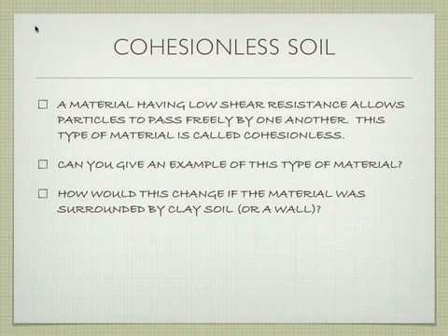But if it's not surrounded by that, it's going to have a tendency to slide, which is going to cause all the issues like you guys have seen with the Pacifica buildings that are hanging on the edge of the cliff that have been there for however many years. Every year they come up on the news, oh, the rain's coming and they're going to fall off the cliff. You guys know what I'm talking about? They're built on sand. There is no boundary holding that sand in. Sand is a cohesionless soil, so when it's exposed, it's going to slip away. Therefore, the building's going to fall over. So this is a fundamental problem with how you built the foundation in the first place. So that's cohesionless soil.